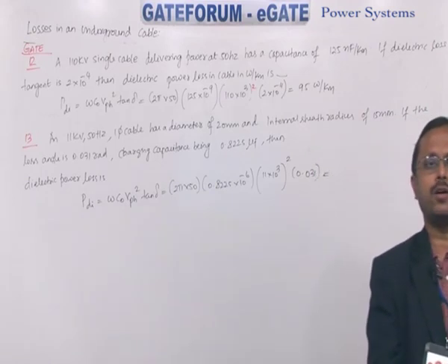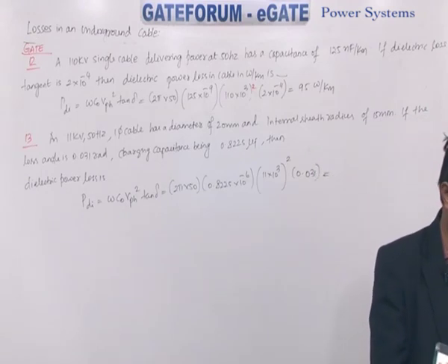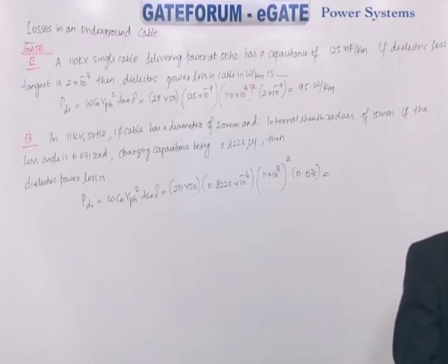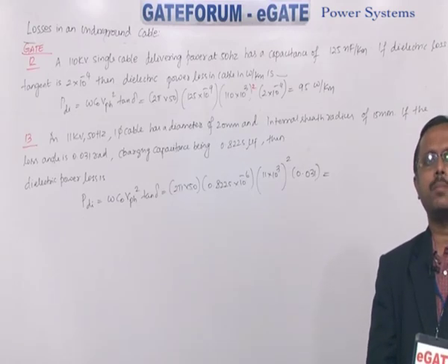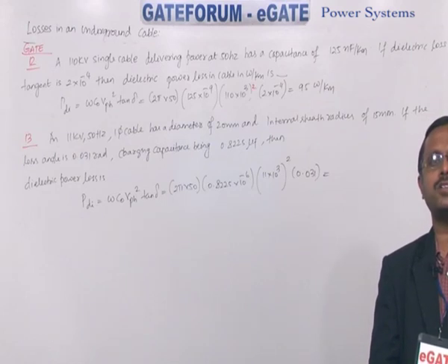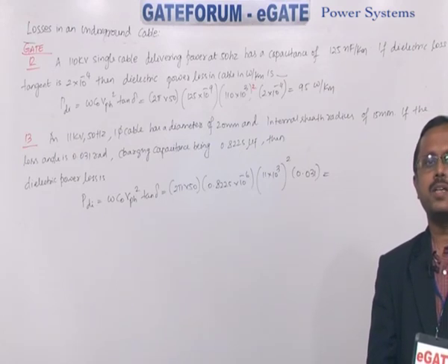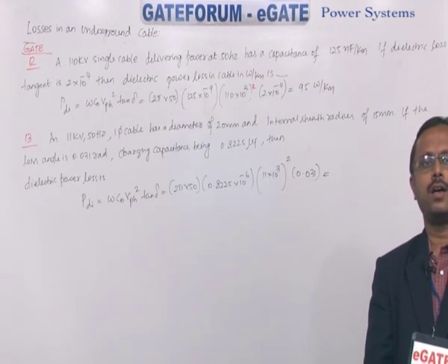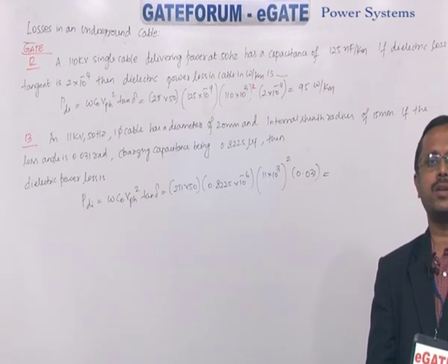Next question is by Gaurav from Bikaner. Which components in a transmission line do not affect stability, and why? Now stability depends on the phase angle, that is the load angle between rotor and stator. That is the first primary component. It is delta that affects the stability.